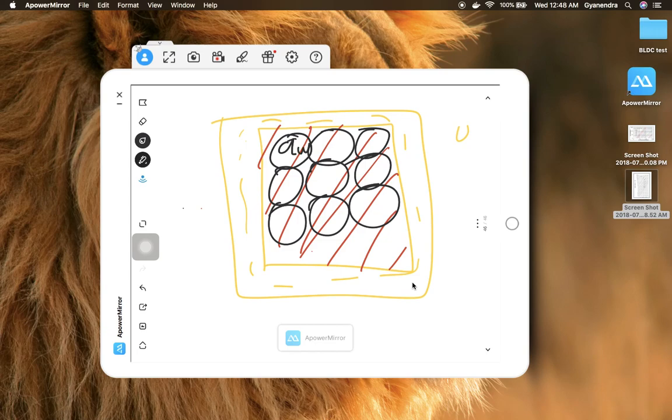Now you will see one very interesting fact: there are areas which are not utilized even after placing the windings very close to each other. So we cannot utilize 100% of the window area for placing the windings; only a few percent can be utilized. That factor is called kw, the window factor, which is defined as the percentage of window area you can utilize for placing the conductors.